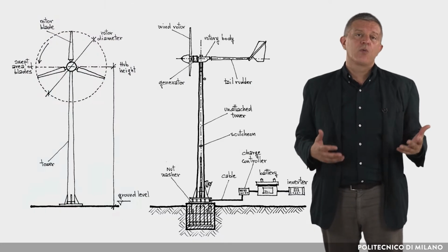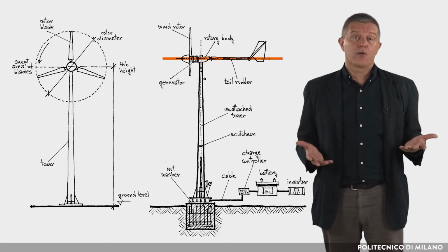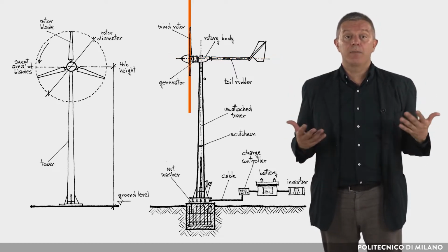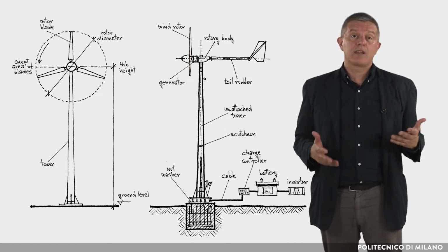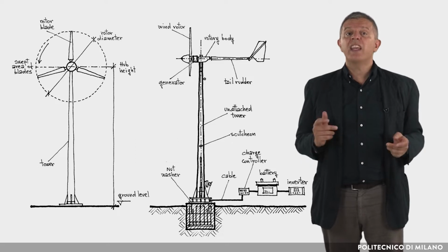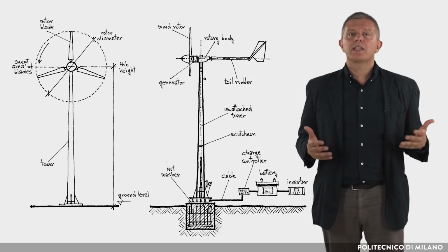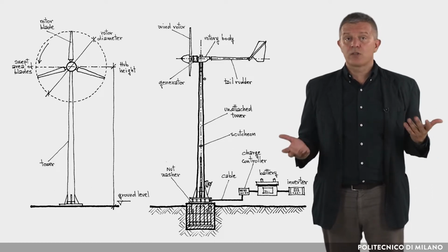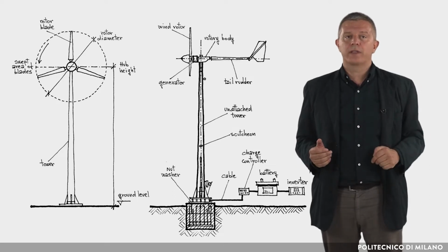In the former, which are the most common, the rotation axis is horizontal and therefore the blades rotate in a vertical plane. A typical horizontal axis wind turbine generally has 3 blades, but there are cases of 2-bladed and even single-blade models. A rudder keeps the blades plane always facing the wind direction. A control system slows down or blocks the rotation speed when there is high wind.